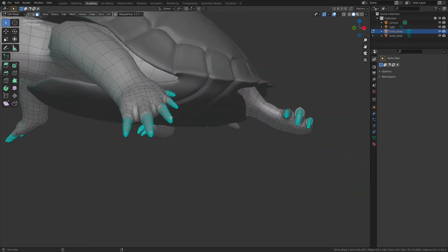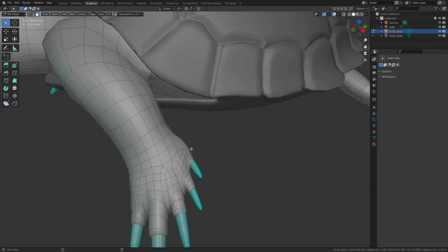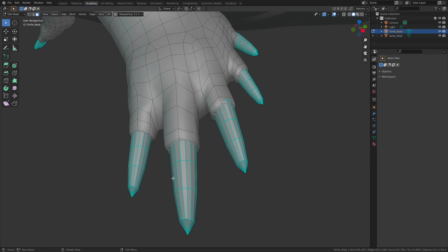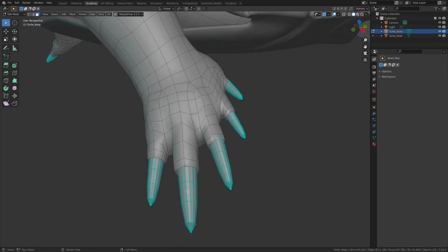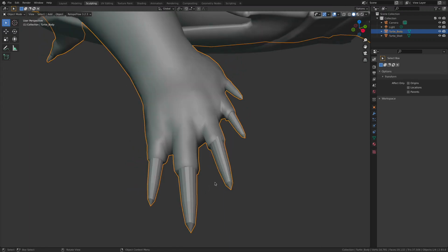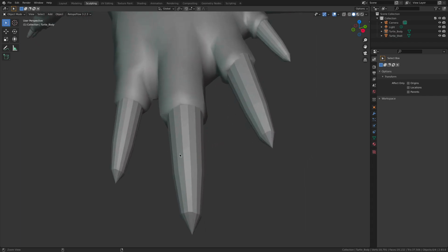And I think what I did on accident is that I forgot to go in and remove all the hard edge tags on the objects for the nails. And it makes sense if you look real carefully. They're very faceted. You can see that the smoothing engine is smoothing each face of the nail independently, and it's not smoothing across. So let's fix it real fast.